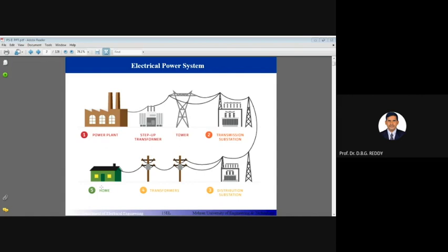So worldwide, majority of long-run power transmission uses the overhead transmission system. Only in unavoidable situations, such as river crossings and national highway crossings, will they use underground cable power transmission. Why? It is costly, but suitable for high load density areas. If there is no other option, then we have to use the last option, the cabling system. But it has good performance compared to other systems. Now see this slide, which covers the electrical power system. Now I am moving to the second one.